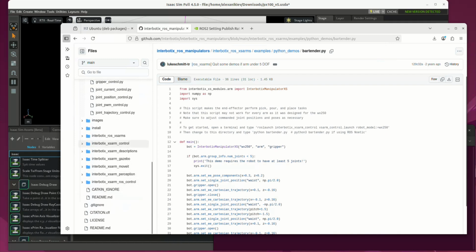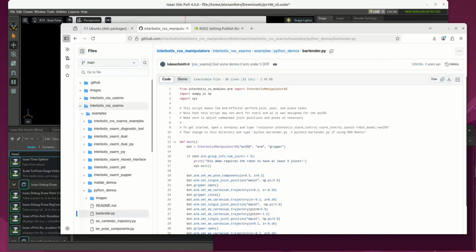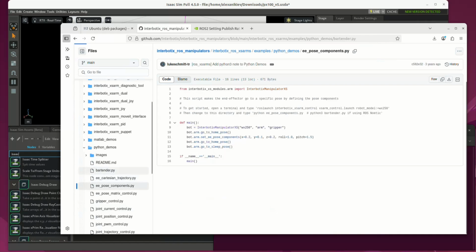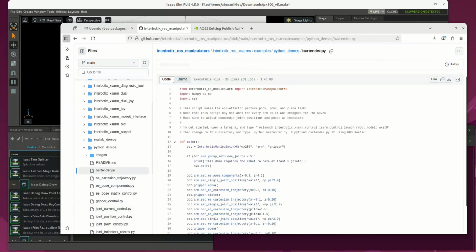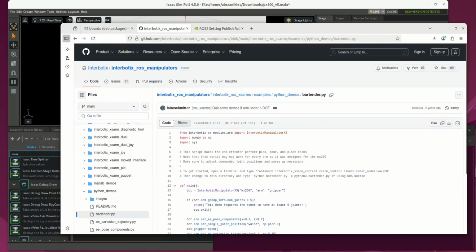We have this Robotics ROS manipulators GitHub that we could use with this arm, PX100. There's a ROS control, there are control examples as well as Python examples. But the thing is that this is built for ROS1, and we'll be using Dynamixel SDK directly for relaying messages and joint state messages to our robot. But this is just a quick illustration of what's available from Trossen AI on the Robotics ROS manipulators GitHub.